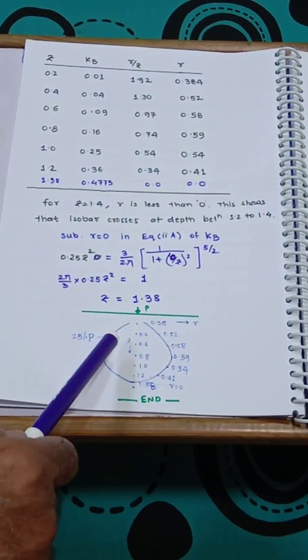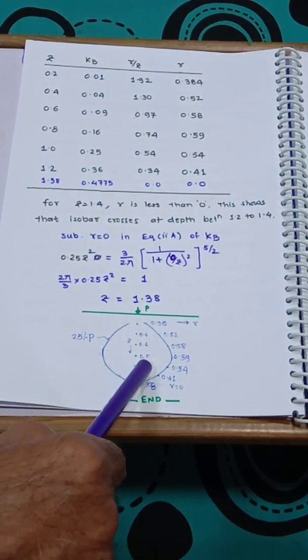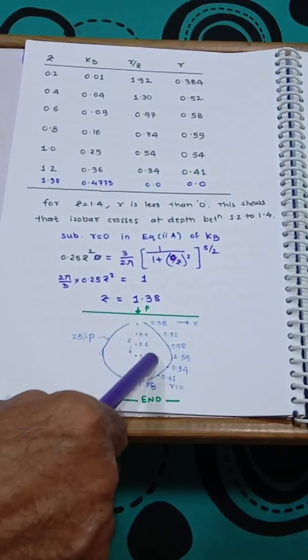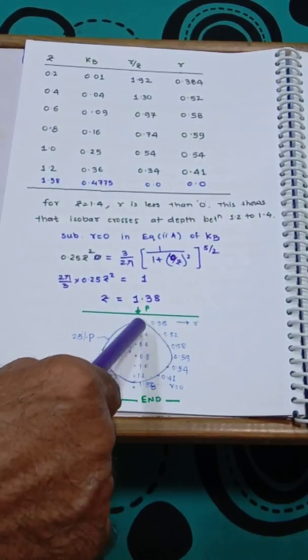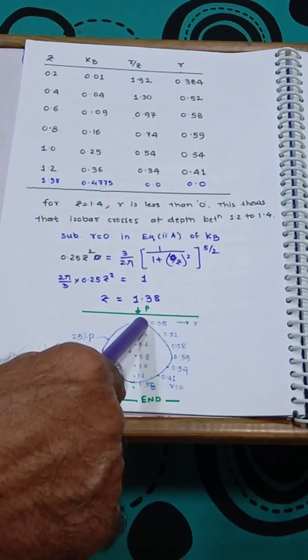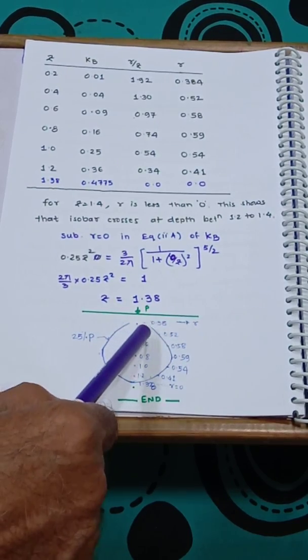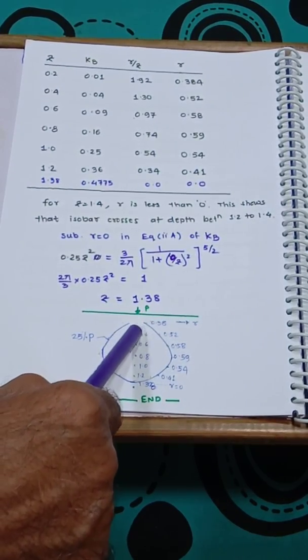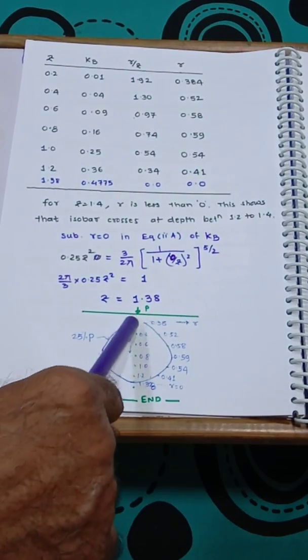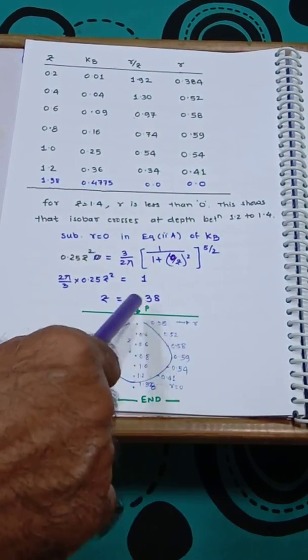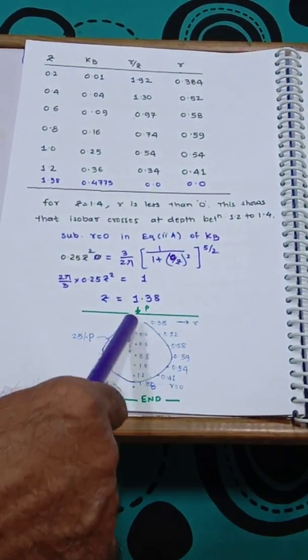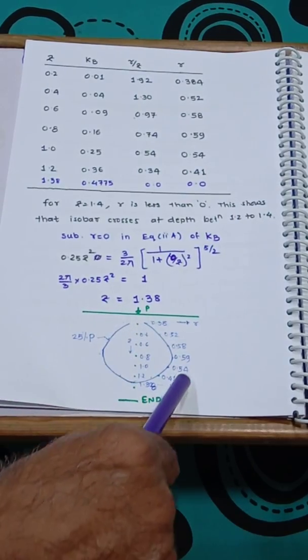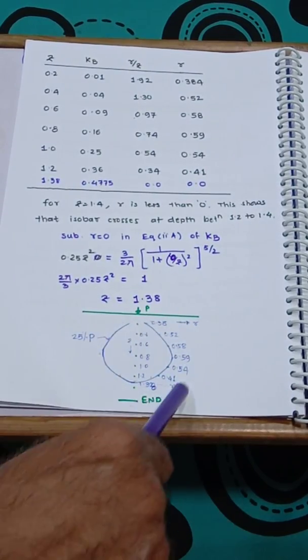If I draw a pressure bulb of 50%, it will go up because stress increases. If it's 75%, again a small isobar, 90% a very small isobar. If I go far away like a 10% pressure bulb, it will move downward and outward.